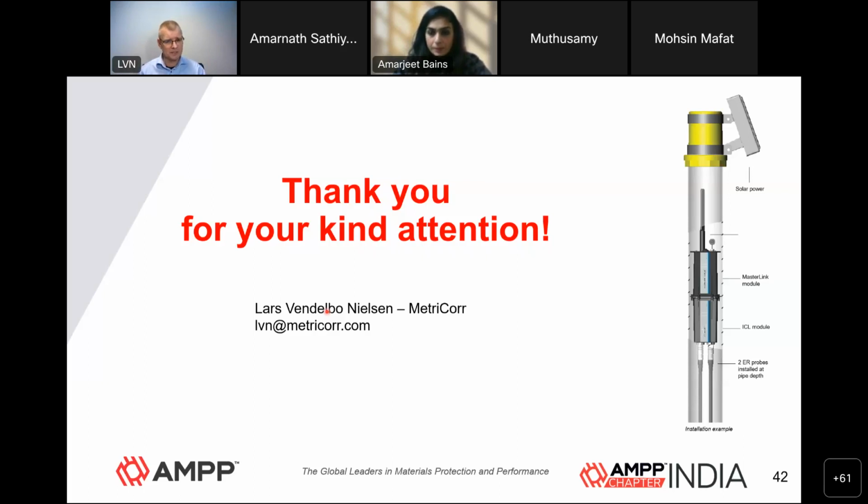But as a general rule of thumb, I would say make sure that you are not excessive with cathodic protection. Minus 950 is to me a better value than minus 1200 millivolts, and that's in the on condition actually.